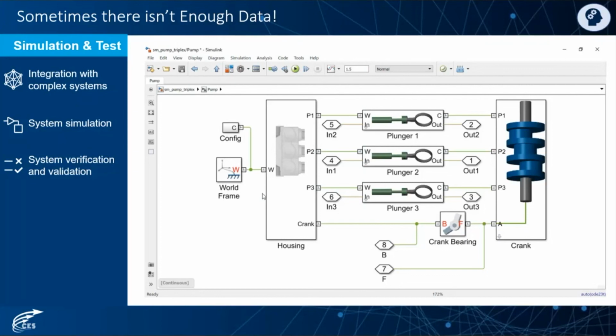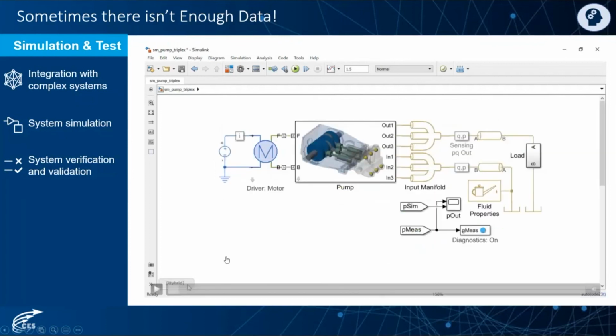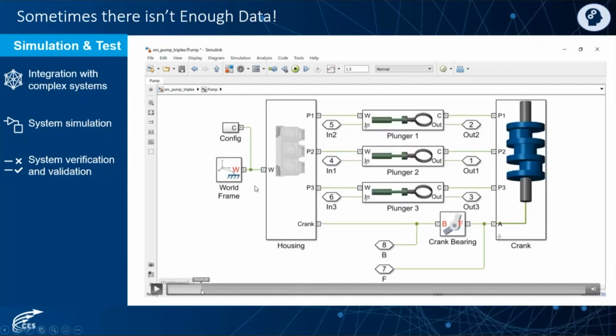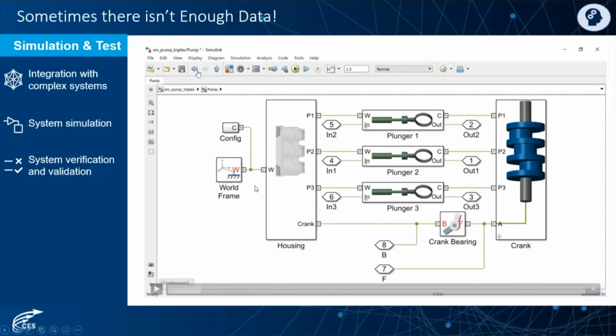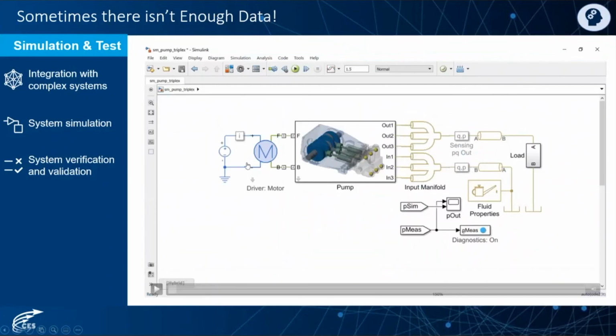Exactly. So here, this is one of the advantages of the flexibility of MATLAB. You have the option to convert to Laplace, but this is not something obligatory. In this example, we are not doing any kind of this transformation. We are actually designing the system using physical components. And Simulink will take this conversion from the physical component itself into the time domain so that it is integrated with the rest of the system inside Simulink. So here you are not actually building a transfer function or any kind of approximation of the device. You are actually building the physics of the device inside the tool, and then Simulink will take care of these conversions at a high level and be able to integrate it with the different aspects of your system.